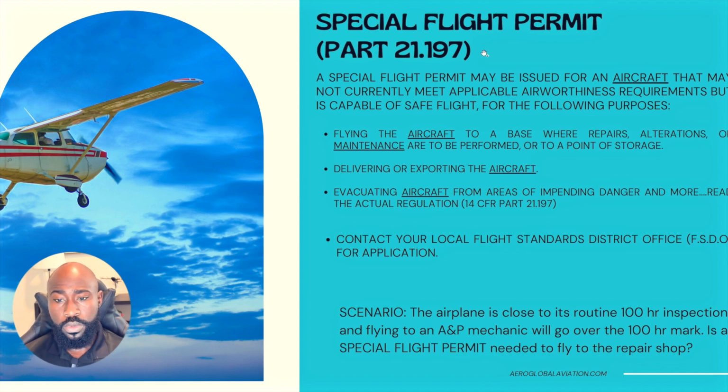To see the full breadth of the circumstances that may require you to obtain a special flight permit, please make sure you read the regulations, but I'll just go over the few we have here. For example, if the aircraft is to be flown to a base where the repairs are going to be made, or where you're going to store the aircraft, you can obtain a special flight permit in this situation. Or if you're delivering or exporting the aircraft. Also, if you're evacuating the aircraft from areas of impending danger, you can obtain a special flight permit for this purpose.